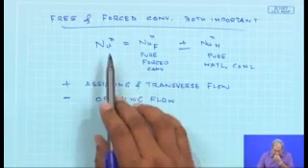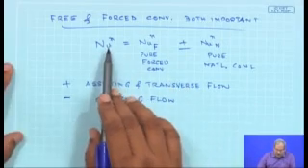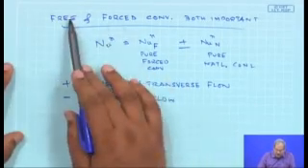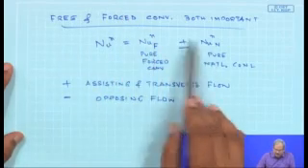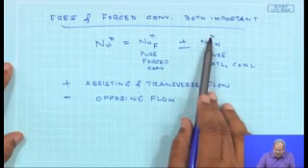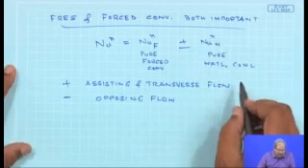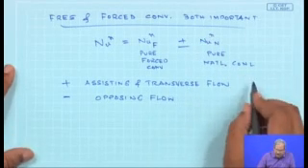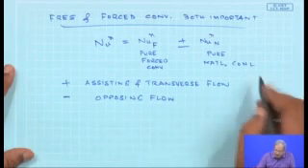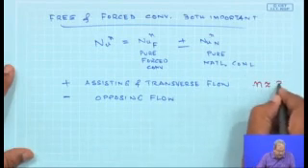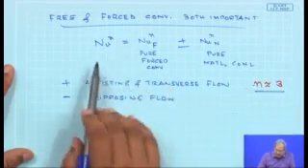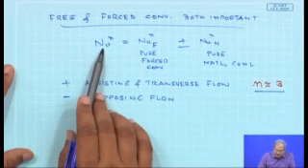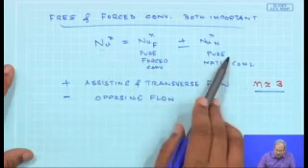So the Nusselt number when both are present is simply an algebraic sum to the power of some coefficient n, where this n is generally taken to be equal to 3. This is only a first approximation to find out the combined heat transfer coefficient when both are present.